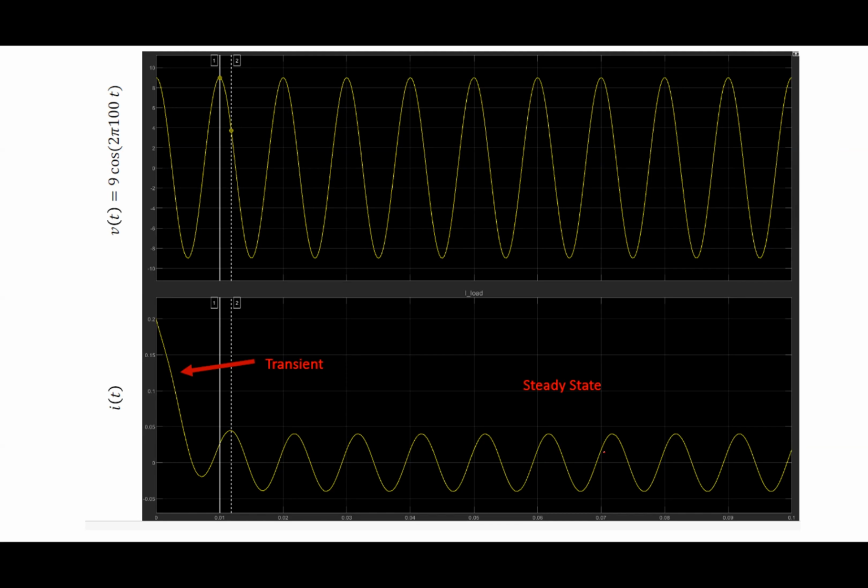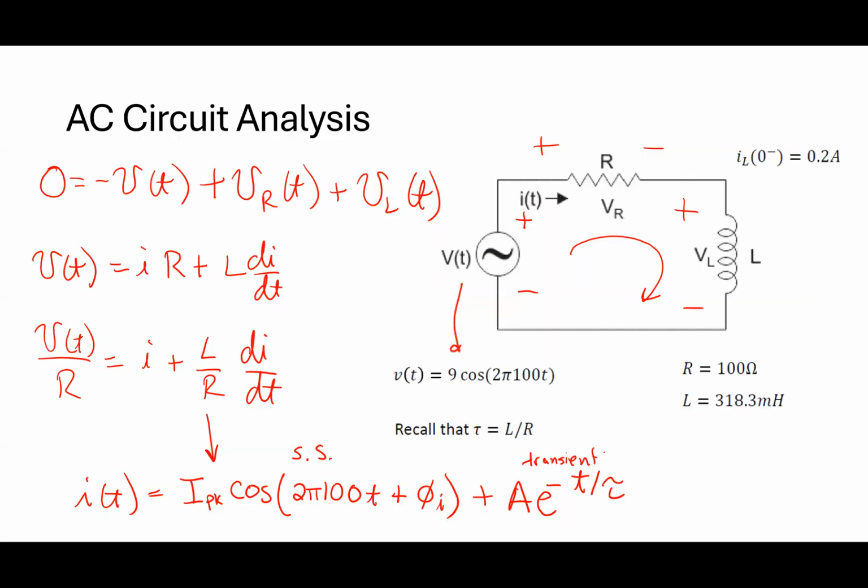Why do you see a flash of light? Because there's an inductor in that circuit, and you're forcing the current to become discontinuous. Current doesn't like to be discontinuous in an inductor because it represents energy storage. That energy that was electrical became light all of a sudden. The same thing happens with the capacitor. If I put a screwdriver across the capacitor, you'll get a similar flash. Energy likes to be stored, and energy that's stored can't just go away. It has to go from one form to another.